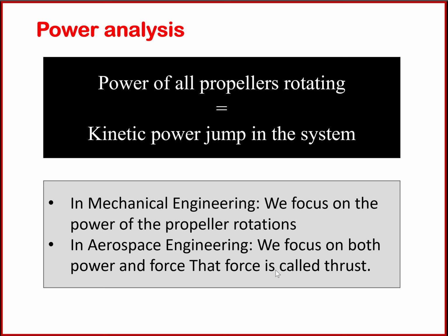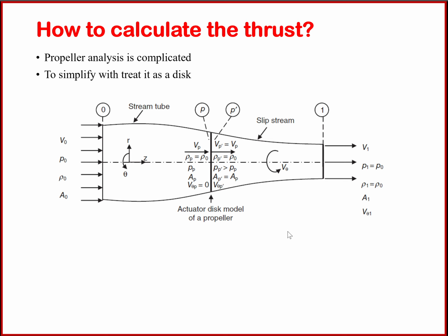So the idea is you use this theoretical framework to calculate thrust for your own propeller, and then measure the thrust using the thrust sense and compare the two with each other. But how can we have a theoretical framework that helps us calculate the thrust force generated by the propellers?